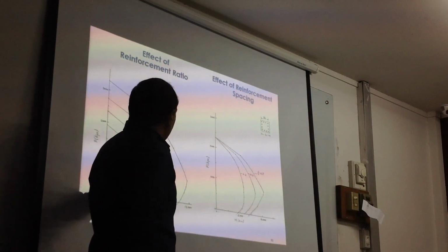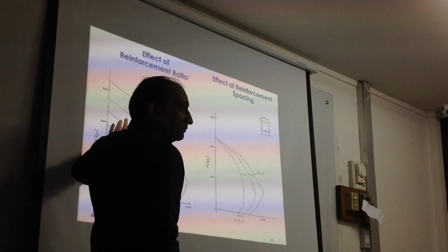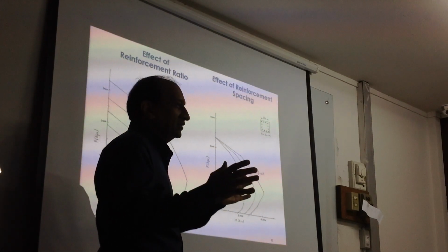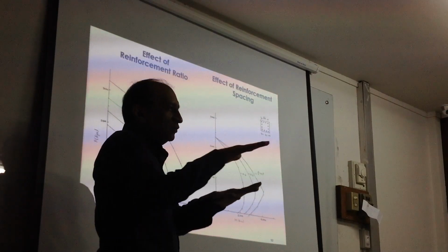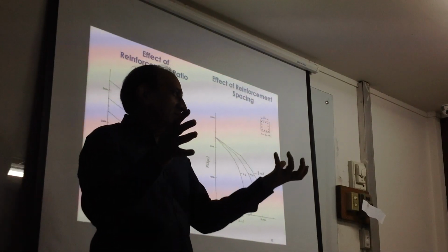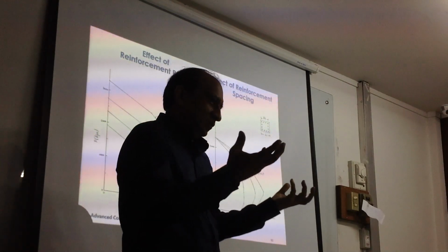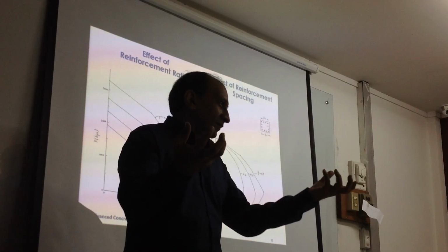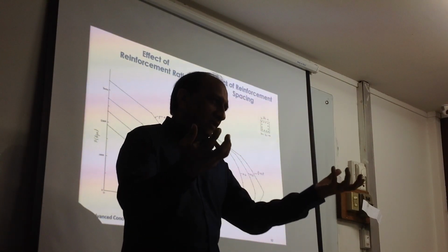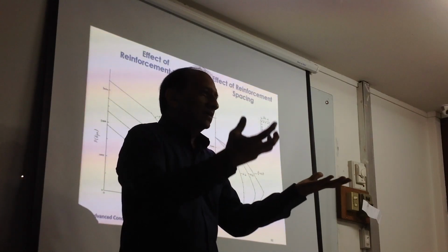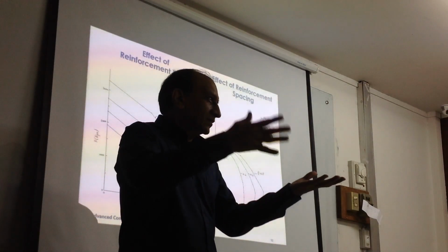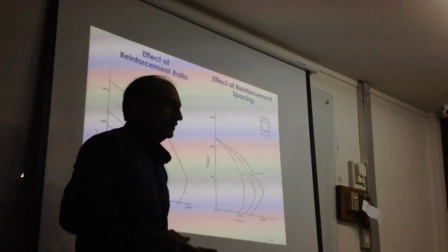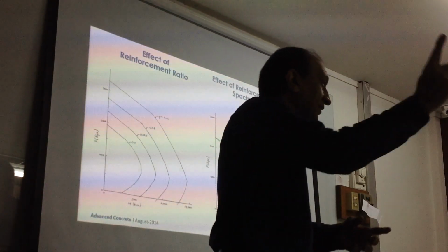Because once you generate for one, the compression for that section is known. It doesn't change. It's only the rebar portion that changes. So the rebar portion, if you calculate separately, compression column, because of our equation, the way it works, you calculate the capacity of steel separately, 1% steel separately, and concrete separately. Concrete you don't need to scale. Steel you simply scale in this way because you know the pattern and you can just add them together later, again without actually having to generate the whole surface.